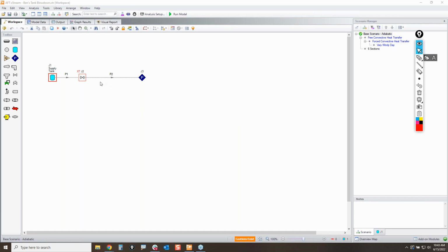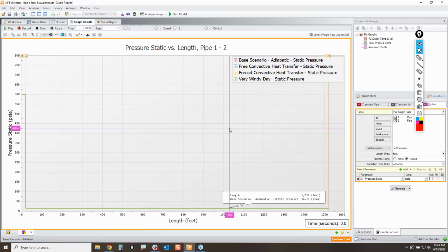It's similar to where Fathom does not yet model filling of evacuated piping systems. So same thing here. You wouldn't have an evacuated system, it would have air in it, but we don't have a mechanism yet that demonstrates that fluid interface boundary traveling down the line. So be aware of that when you get into your analysis.